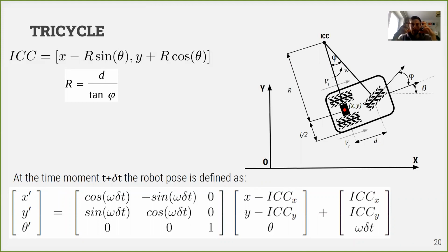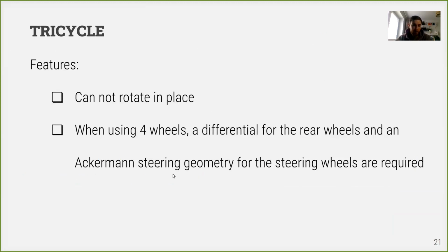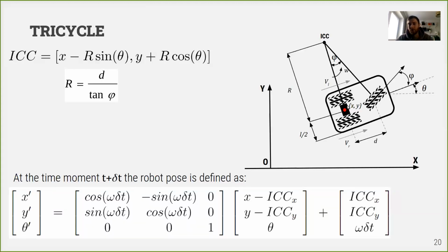and if these two wheels are hard connected, then it means that one wheel will be slipping all the time, because the wheel which is moving on a bigger arc will have to rotate faster. If there is a hard connection, the wheel which is moving on a smaller radius will have to slip in order to keep up with the wheel which is moving on a bigger radius. And this is why Ackermann steering geometry is a concept which is widely used in our cars, because actually this is quite similar to the car geometry, except with one wheel in the steering axle instead of two.